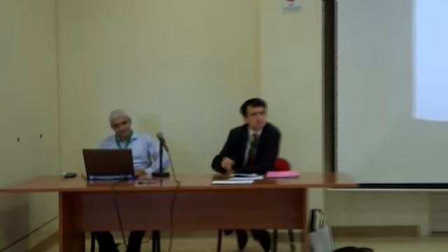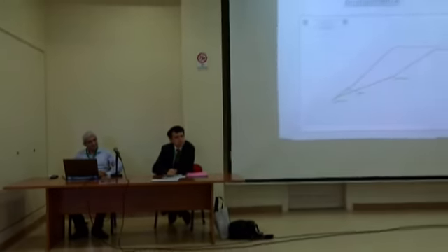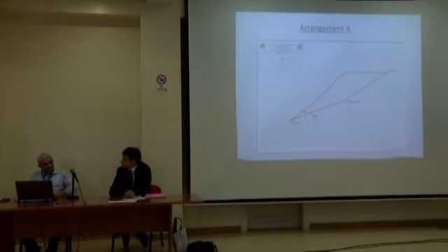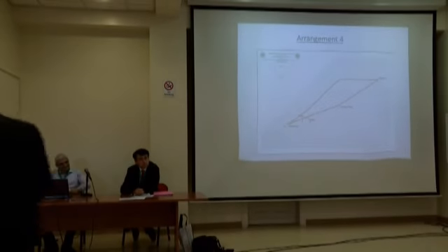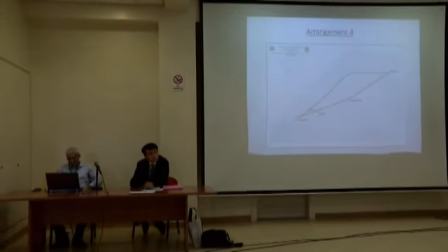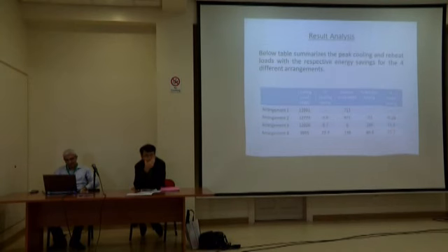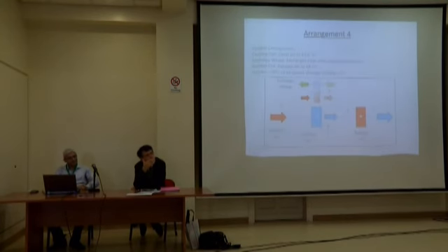I try to understand in the psychrometric chart, from point 1 to point 2, this is the portion of the air passed through the cooling coil, right? 68% of the air passes through the cooling coil. Right, 68% is the percentage through the cooling coil. The bypass is the 32%, right?